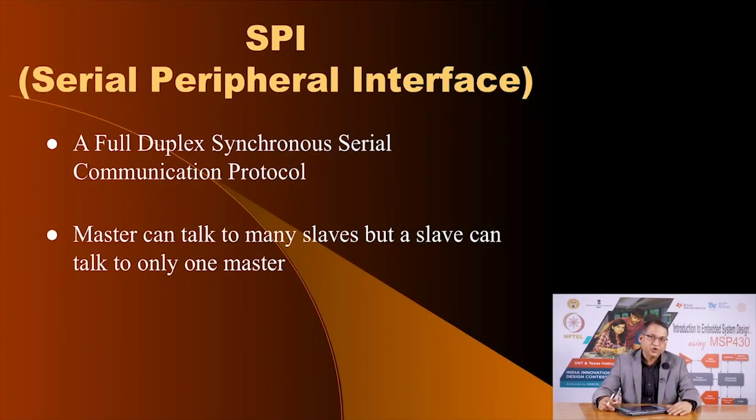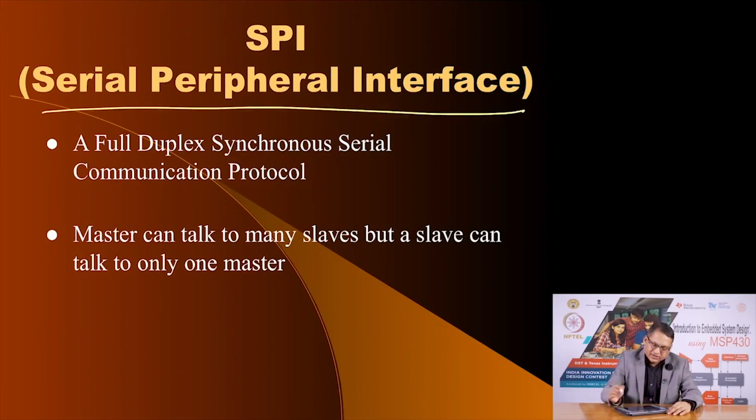So, this is as far as the UART protocol is concerned. The second protocol that is available on MSP430 is the serial peripheral interface. This is full duplex and synchronous. The previous protocol was asynchronous, which means there was no separate clock being sent, but here you have to send a separate clock. You can create a network of devices using SPI, and you have a master, and you can have one slave or multiple slaves, and you can have full duplex communication.